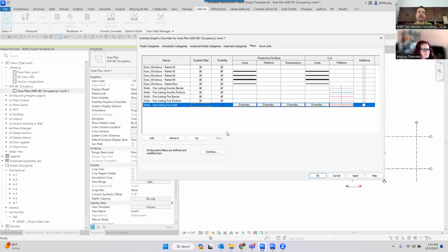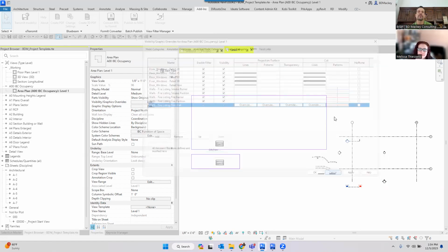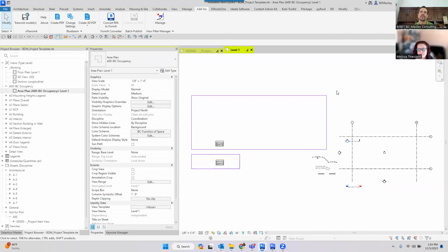When we got this capability, it was for some of these filters that are, in my mind, somewhat critical, like changing the color of the code. I have filters for turning off elevations and linked grids and levels, etc. I might want all of those in every single view template because now we can choose to disable those, right? In the past, all we could do was go remove all the colors, and it was basically, why did you add the filter?